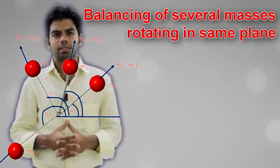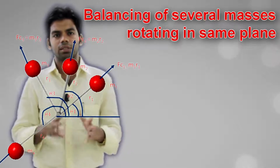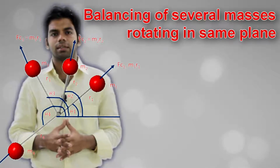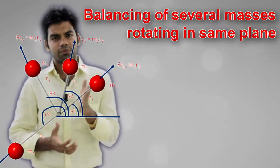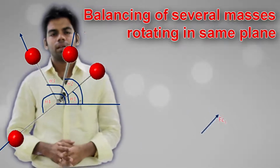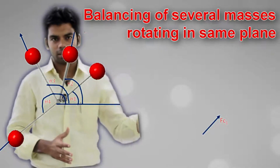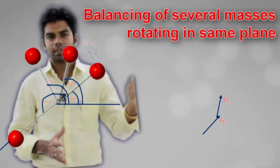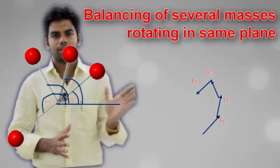Okay, so how to find the resultant? As we know, if we have different vectors and want to find the resultant of all the vectors, we can put those vectors in the form of a polygon, and the remaining side will give us the resultant. This is polygon law of vector. So we will put all these vectors as different sides of the polygon. We will put this vector Fc1 as one side of polygon. Now the head of this Fc1 will become the tail of Fc2, and the Fc2 vector is placed at the head of Fc1. Similarly, Fc3 vector is placed at head of Fc2, and Fc4 vector is placed at head of Fc3, as you can see in the figure.